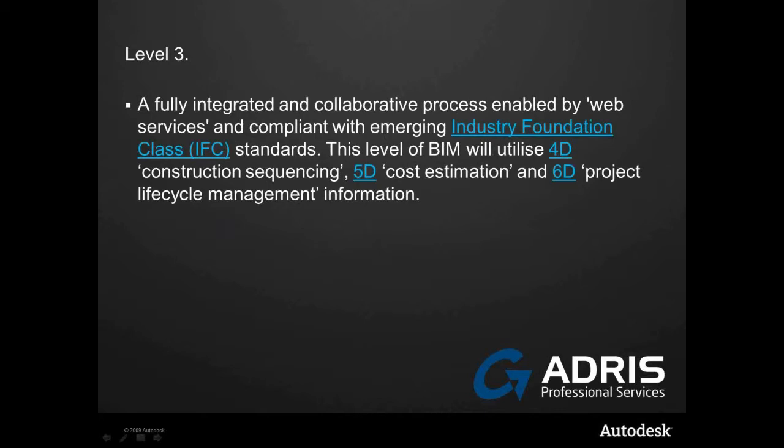So this is creating a fully integrated and collaborative process enabled by some sort of web service, again, by some sort of portal, possibly compliant with IFC, so the data is formatted in a certain way, again, using the 4D construction sequencing, the 5D cost estimation, and this time 6D project lifecycle management. So this is now doing something with the data. So this is about working concurrently and then passing this data over to a user who can then interrogate this data and do something with this data.